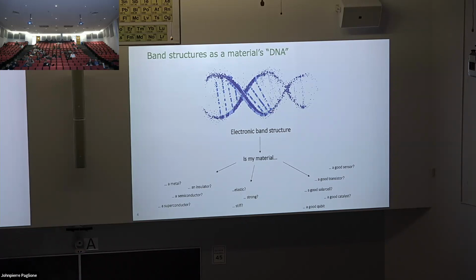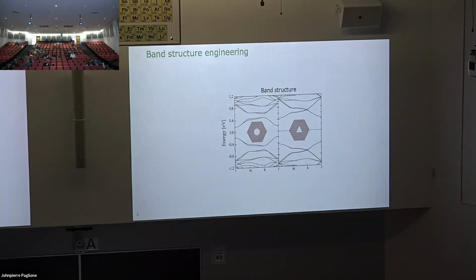So in the past, I was working on trying to make graphene a semiconductor. This is what I just mentioned. We want to somehow have a range of energies in graphene where conductivity is turned off. The framework of all of this is what's called band structure engineering. So maybe you can do things to your material that fundamentally change how it behaves. It's not just some effective change, it's really the intrinsic properties that you're changing. And effectively, you're making a new material when you are changing the band structure. It is something new as soon as the band structure is different.